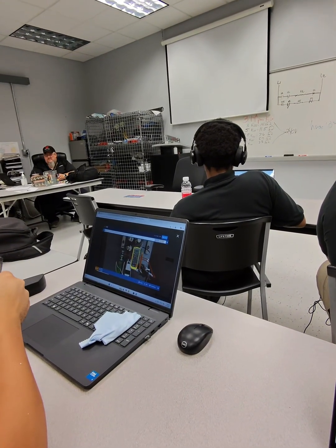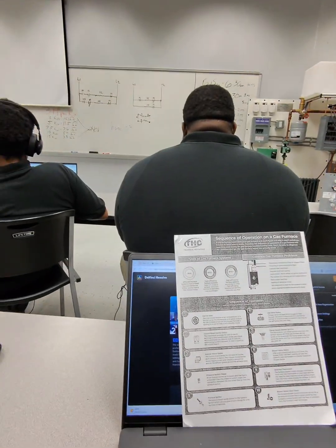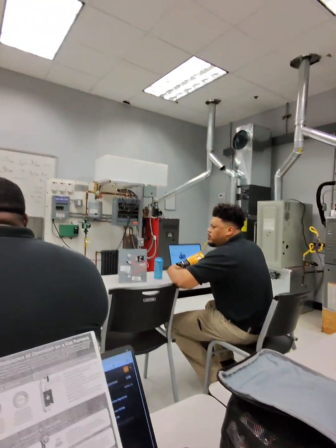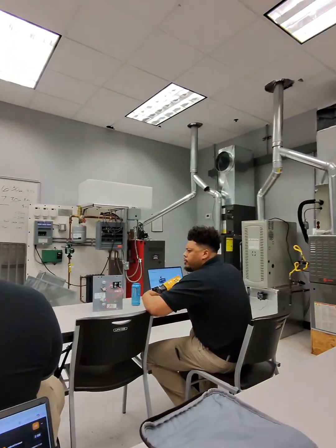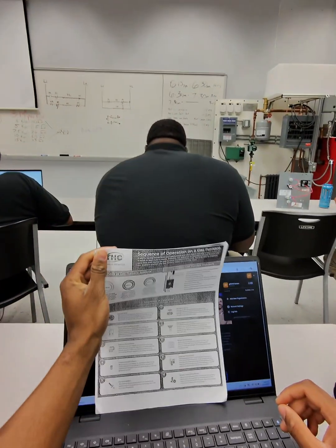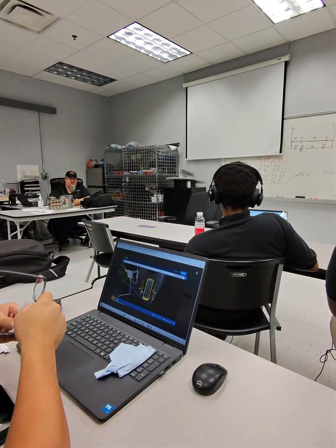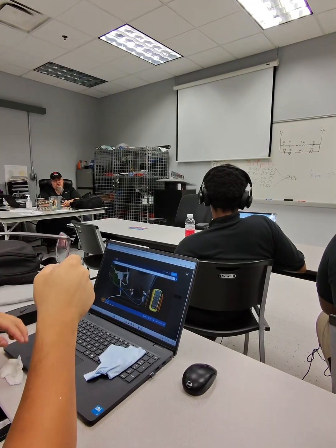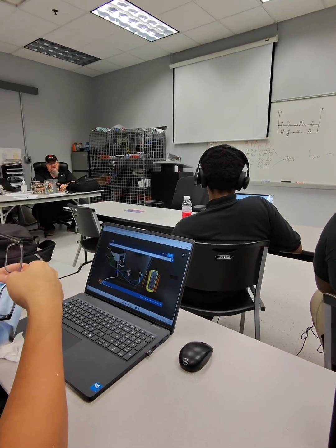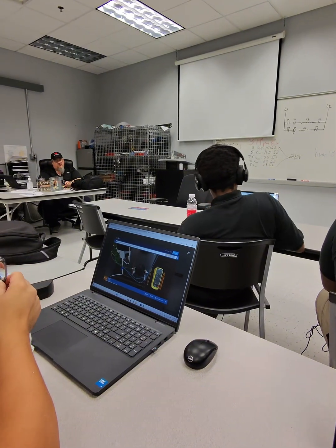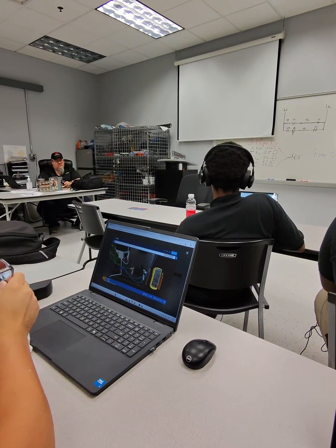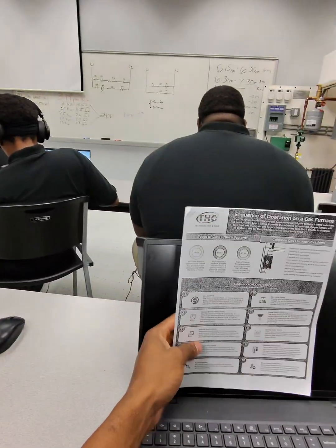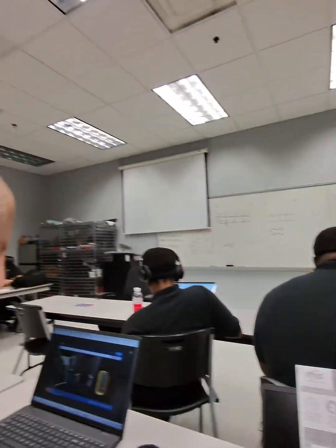Alright. Y'all got that? Y'all remember that? Yeah, man. I mean, we got it right here. It's just the sequence of operation. I have a class that's about to graduate, and I took them out there to look at a package unit. And they didn't know what a rollout switch was, where the high limit was. None of that.